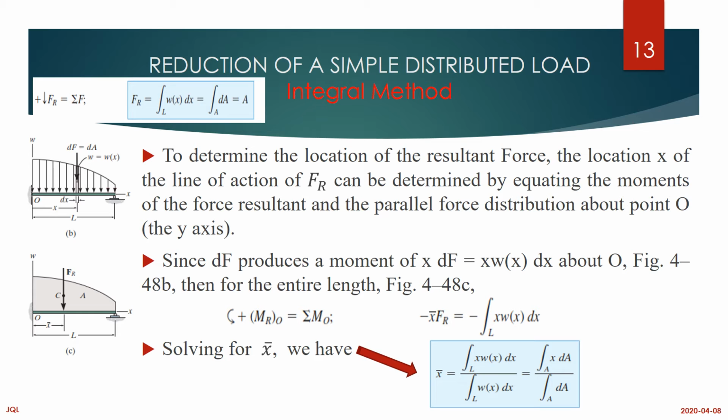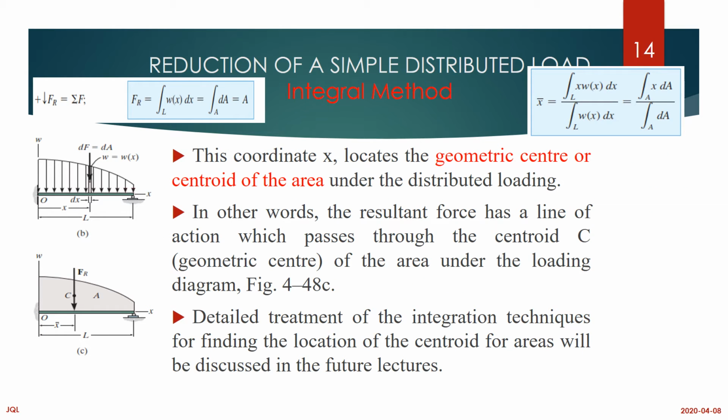If you remember this equation, we are just doing some integrations, getting the area of that curve, which happens to be this curve. So for us to get the length, x is the volume divided by the area. This coordinate x locates the geometric center or centroid of the area under the distributed loading.